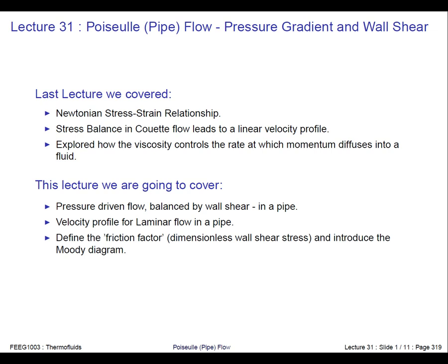And that also allows us to talk a little bit more about turbulent boundary layers. These are really important because turbulent boundary layers generate a lot more pressure drop than laminar boundary layers, and we'd like to try and control this and reduce it if we can as an engineer.